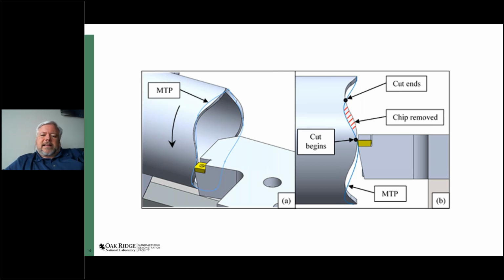In fact, it's kind of interesting. If I play around with the conditions, I can program the lengths of the chip. So I know I don't want them really long and stringy, but sometimes I also want them to have a little bit of length, because some people collect them up and compact them. And if they're too short, then when you put them in the compactor, they spring back and don't lock together.